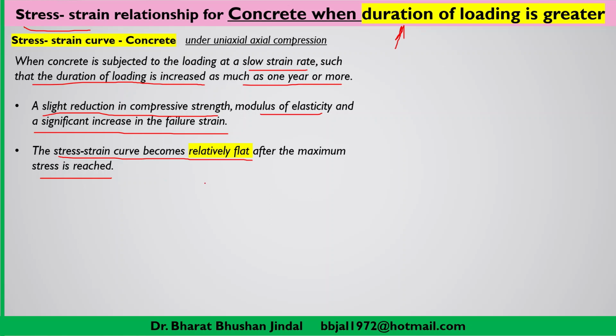In the previous graph, the stress strain curve was a linear relation up to some stress level. After that, it becomes a parabola, a curve type of shape, and after the maximum stress level is reached, the curve again falls. But when the loading is for a longer duration of time, the stress strain curve becomes relatively flat after the maximum stress is reached.